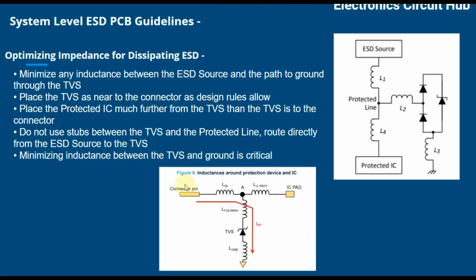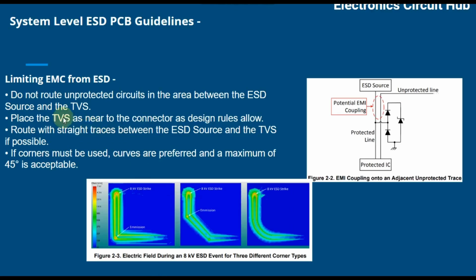So let's say you have a connector here and you are placing the ESD diode here. You have to minimize the inductance of this path, and this should be as far away from your source. Another system-level ESD PCB design guideline is limiting EMC from ESD.